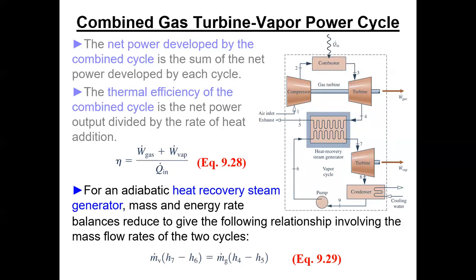So for adiabatic, which means we don't have any stray heat losses, when you work a problem like this at this simple level, this is where you join the cycle. Usually you'll know a mass flow rate either on the Brayton cycle side of the air or on the water side. This allows you to calculate the one that you don't know after you've found all of the enthalpies.